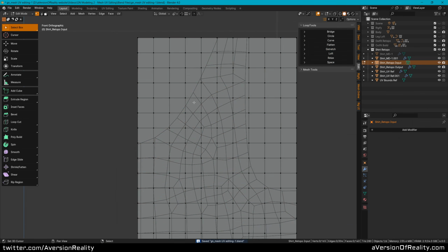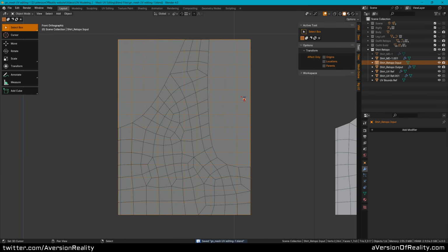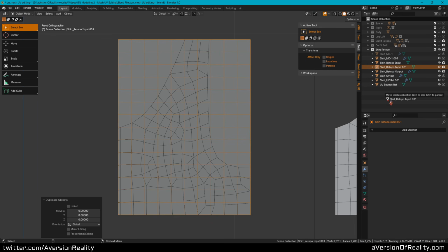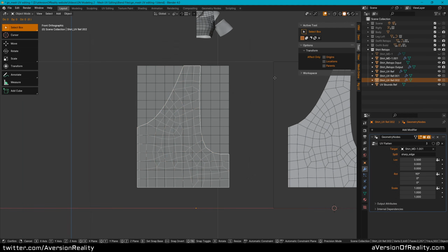So I just want to cut out everything outside the pattern. So I could go through with the knife tool and start doing one for every vertex, and this is kind of manual and tedious. So there's an easier way to do that process, which is I'm going to copy this, because this is a live GeoNodes mesh, or not this one, copy that.